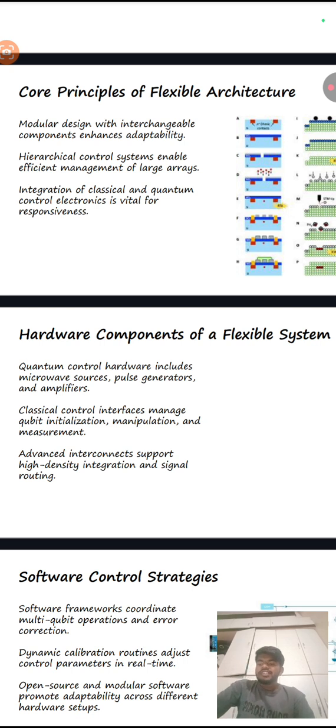And the challenges: signal integrity and noise at cryogenic temperatures, calibration drift and variability across qubits, integration with error correction schemes, and power dissipation limits in the cryogenic environment. Why it matters: building a flexible, scalable control architecture is critical for transitioning from small scalable demonstrations to full-scale fault-tolerant quantum computers. The architecture manages thermal constraints and resource sharing while remaining adaptable to different qubit technologies and software requirements.